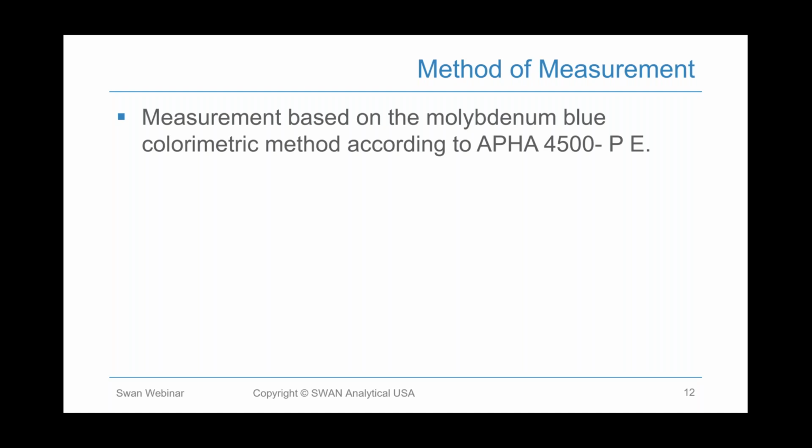We've got our coupons out in the system that we're going around and collecting. We're looking to see how we're doing long term for corrosion control, but how are we doing on a daily and hourly basis to make sure this phosphate that we're putting in the system is getting where we want it to go at the levels that we want it to be?